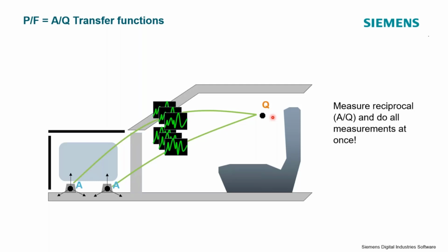And realistically, I'm still going to be taking averages here. When you're doing transfer function measurements, you're always going to want to take a bunch of averages so that no individual hit or excitation is taken by itself. You can always have outliers. But the real benefit is I'm getting 6 for every one measurement I do. And this is the real benefit when you have something that can generate a measurable Q, like a Q source. So this is why we are interested in these devices, is that we can play some of these games and get some really interesting measurements.